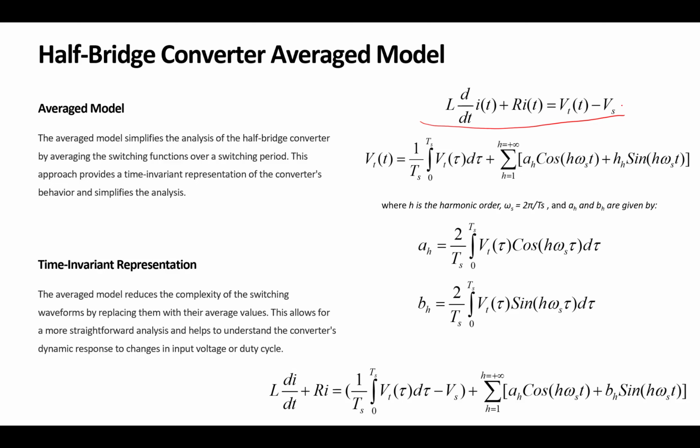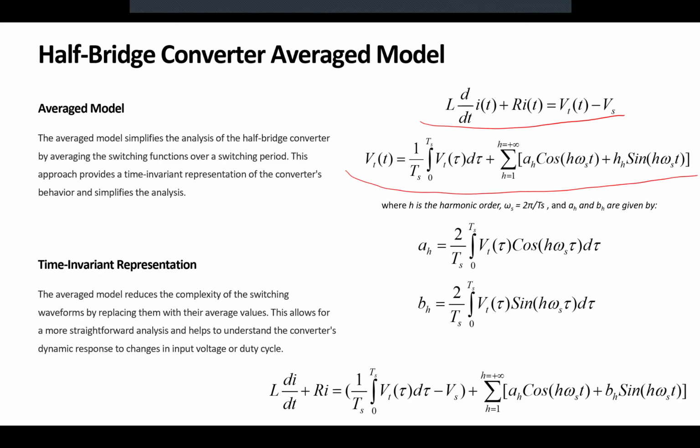Now, as we discussed previously, based on the inspiration that we had from the Fourier series, we could describe our voltage with three types of components: a DC component or offset, the main component, which was h equal to 1, and the rest of the frequencies, which were our distortion, which we call harmonics. Those were the three main components that the Fourier series would give us if we apply it to that arbitrary time-variant waveform.